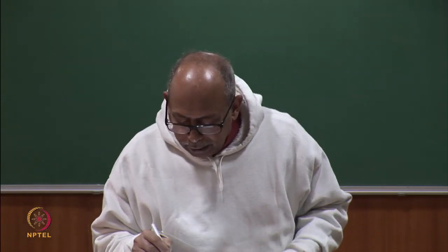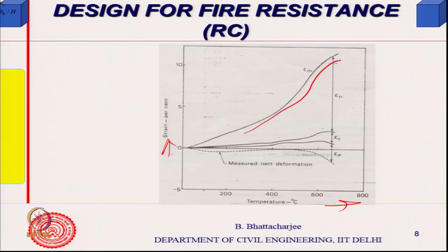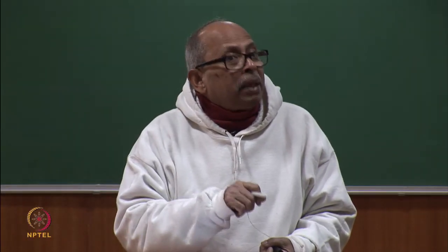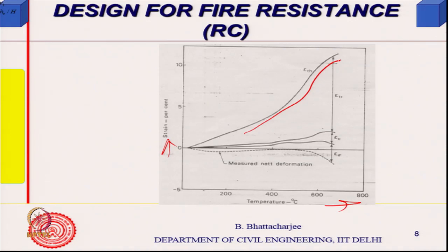There will be some amount of thermal expansion. I put it under compression, remember. So, the compression is there, I am heating it, some amount of thermal expansion will be there, and it will compensate the compression. So, this is total thermal expansion, and you might finally find that there is an overall expansion. So, this is the thermal part, the compression part, then there could be some part due to creep.